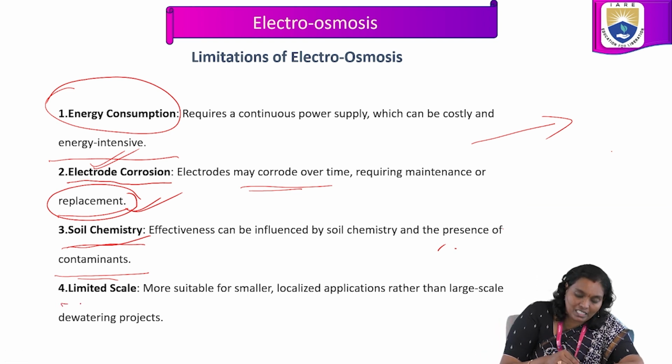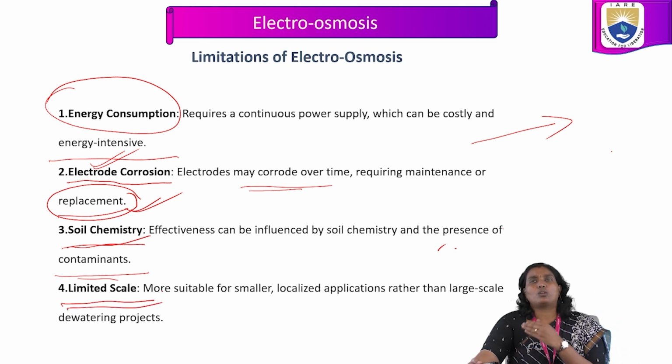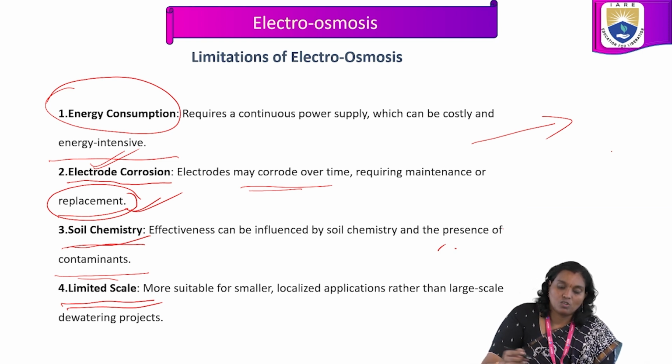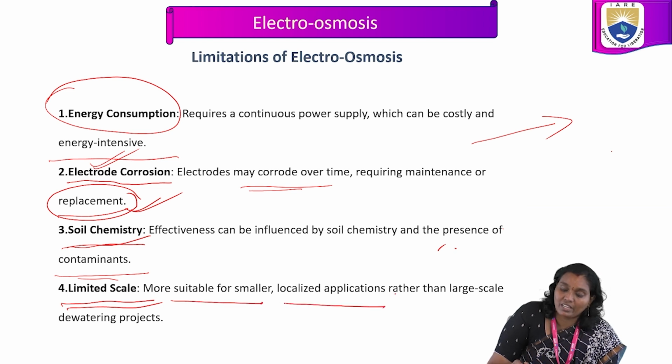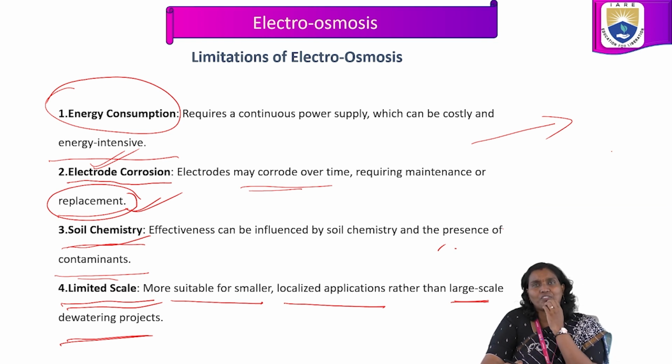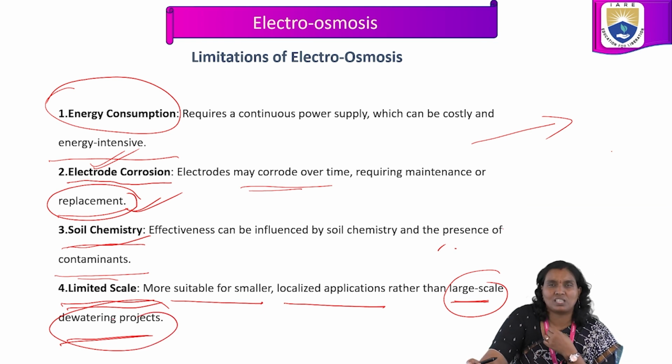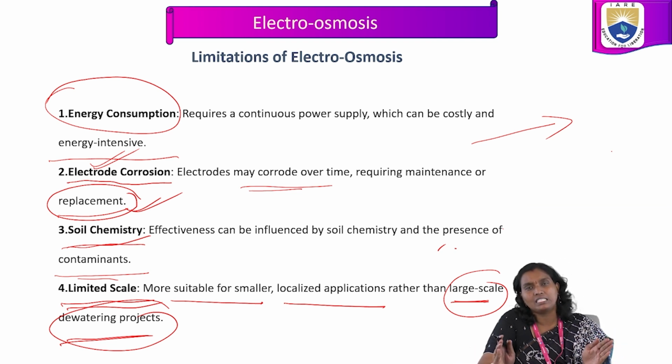The next one is limited scale. It is more suitable for smaller localized applications rather than large scale dewatering projects. This is one of the major limitations: for large scale dewatering projects, we are not going to suggest or use this electro osmosis dewatering technique. It is confined to smaller and localized applications only.